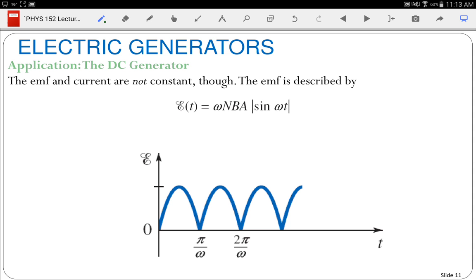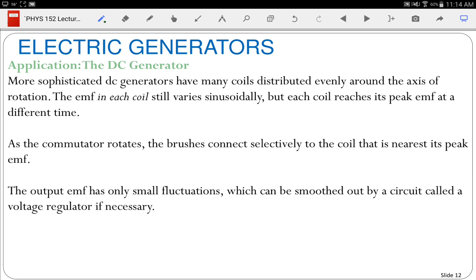So here's where I have the figure for what a rectified generator looks like. Something that is now DC. Notice DC does not mean constant. Batteries were constant. DC just means that you always have this side's positive and this side's negative. But the voltage here is clearly fluctuating. It's called rectified because it's been converted to a DC. It's been made right.